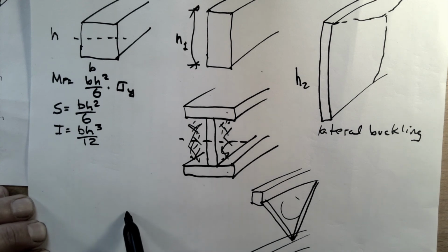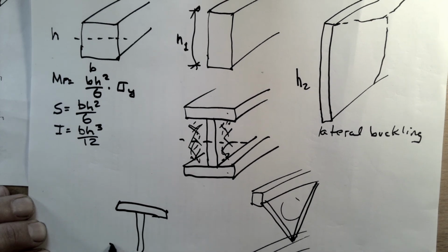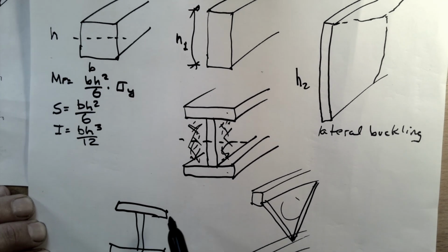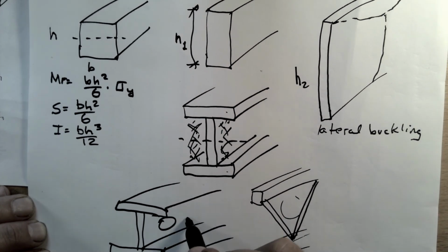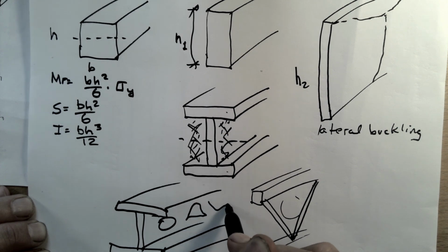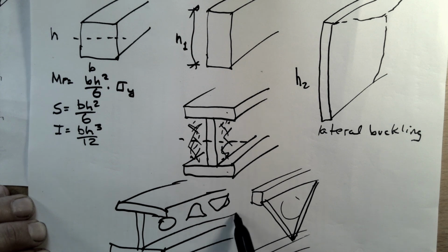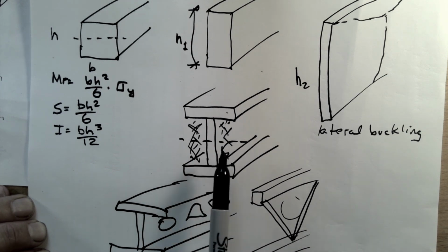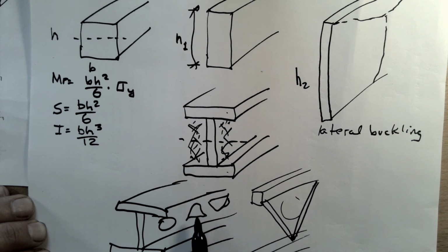And intermediate to these are things called castellated beams, which you might see sometimes, which will have holes or triangles cut into them. And they cut into the webs. So you can see how it's a step from the beam to the perforated beam to the truss.